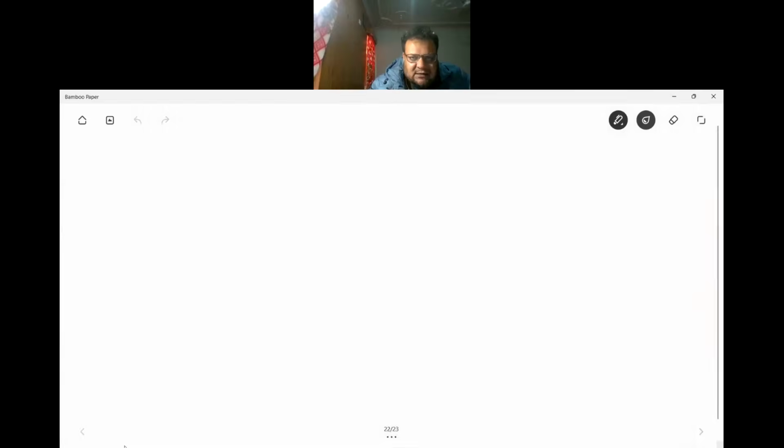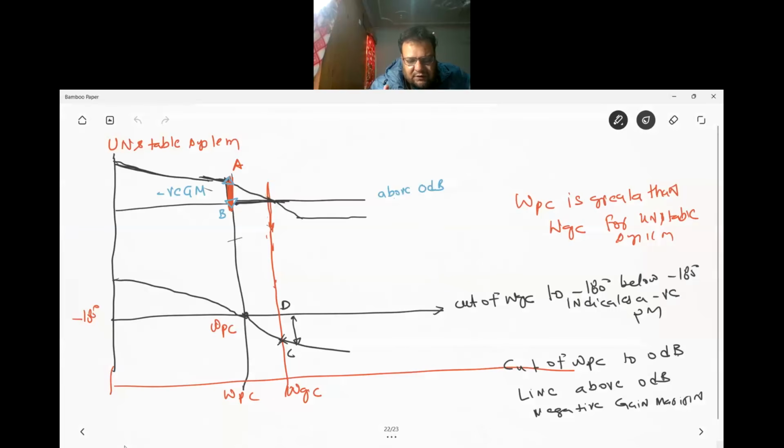So this system is stable. Just remember: phase crossover frequency greater than gain crossover frequency, then it is a stable system. Phase crossover frequency less than gain crossover frequency, then it is unstable.